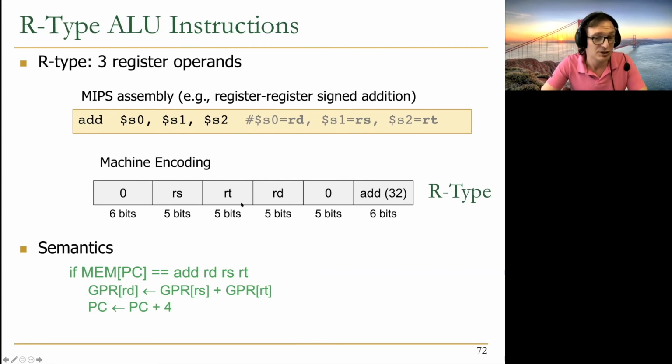Okay, so you need to take specific bits in the instruction, which is this encoding, and use them to index the register file as register IDs, like these RS bits and then the RT bits, and then use this one as the destination register ID and do the addition in the ALU. Concurrently, you increment the program counter by 4. Okay, that's the idea. And we need to supply the data path to be able to do that, right?